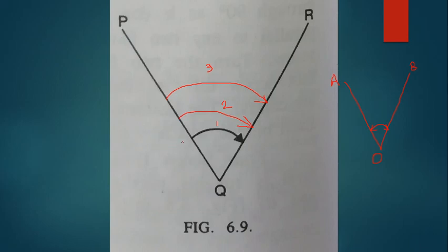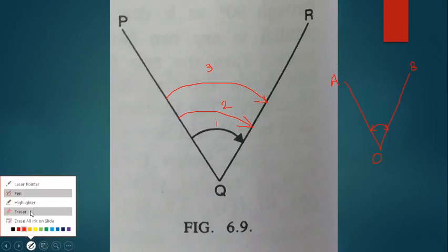Okay, now again you can repeat the process. So again you are going to release the upper clamp here and rotate the telescope to approximately bisect the ranging rod R, and then for exact bisection you may use the upper tangent screw. Once bisection is completed for the first set, I'll erase those two sets.